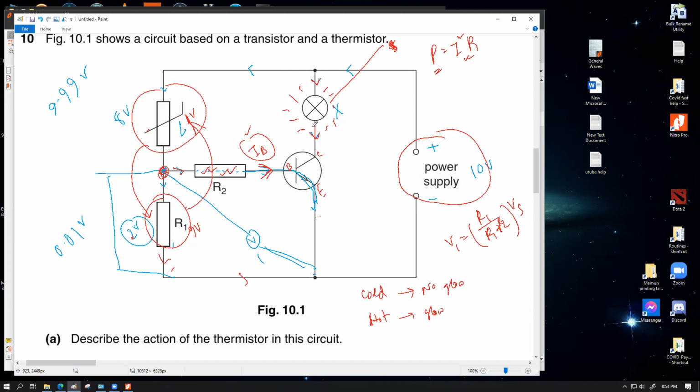So you want to set up a certain warning mechanism within the cold storage device, where at least this thermistor part should be placed within the cold storage. If the temperature goes above 4 degrees, then some sort of light should glow up in some warning location, let's say in the office room of that cold storage, that would let them know that the temperature is rising, so you better check out your refrigeration system.